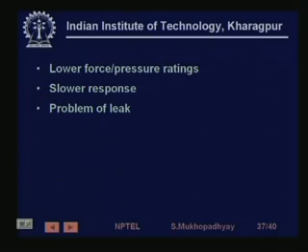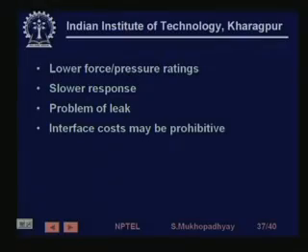In pneumatic there is a problem of leak, and leak is not so easy to determine, but it will reduce the efficiency of the system. If you want to prevent leak, that will increase maintenance cost. It will also make the seals tighter and will increase friction, which in turn will cause a further fall in efficiency. So, leak is a big problem for pneumatic systems.